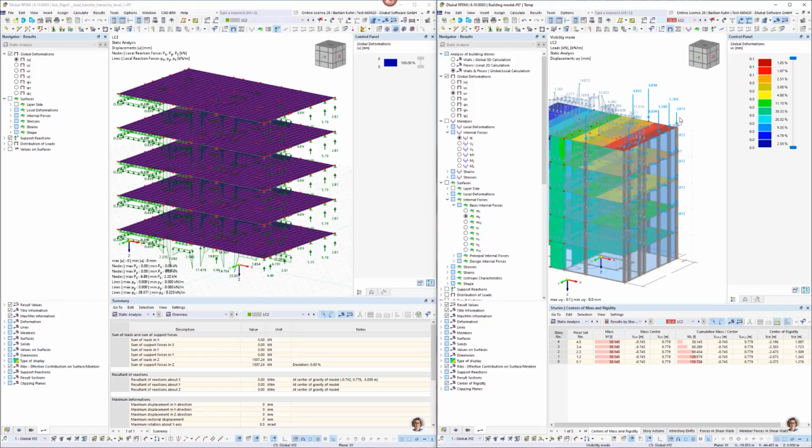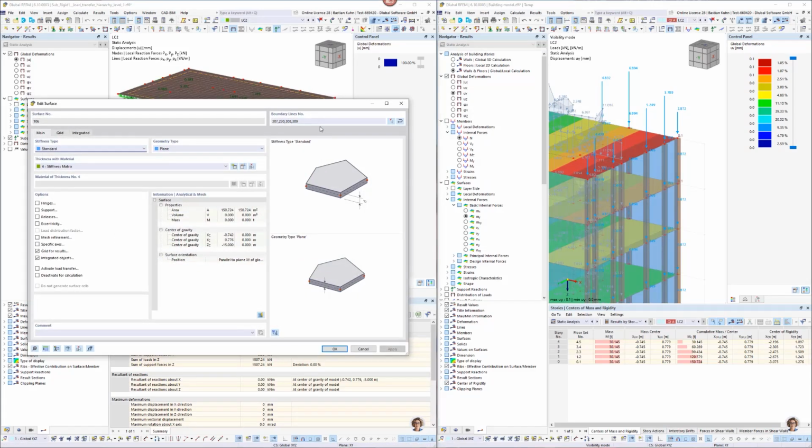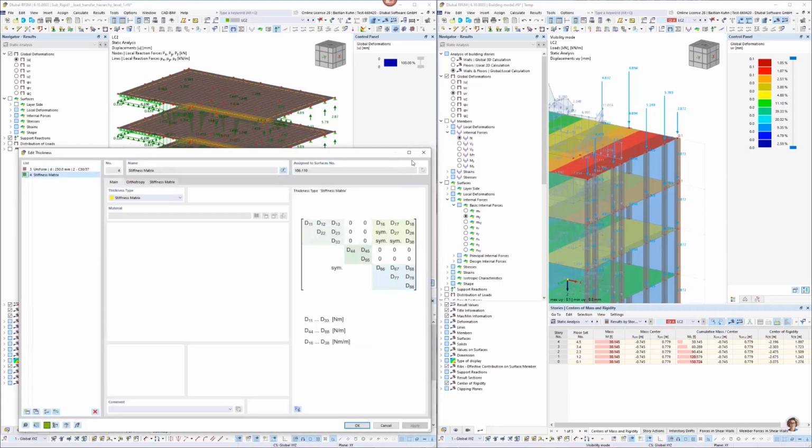So if you look for this, you see that here what is done in the global 3D model is the force that's separated via the load transfer function is what I receive as a result in this model that I created. And this, as I said already, contains the supports hinged here on every part and a very stiff stiffness matrix.